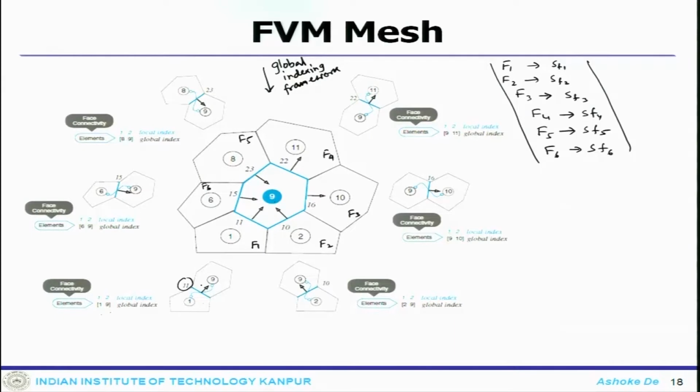That means for 2D cases, every 2D system, each element is associated with these two elements. As we said, when we consider element number 1, the surface vector is going outward. For element number 9, the surface vector at surface 11 is going inward. So, when it is going inward, it should be with a negative sign of that surface vector.